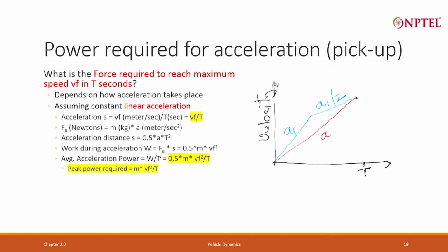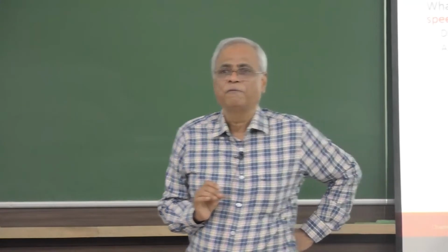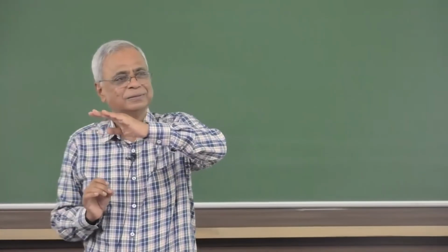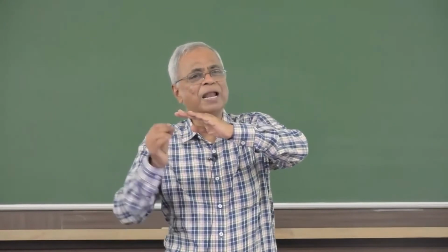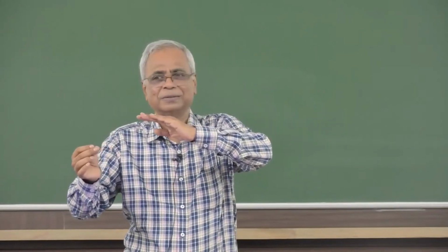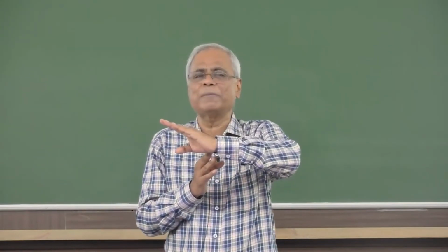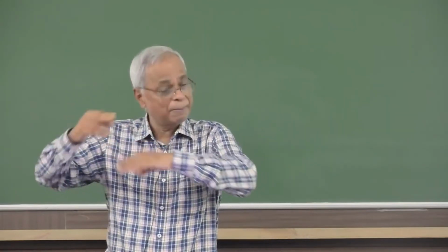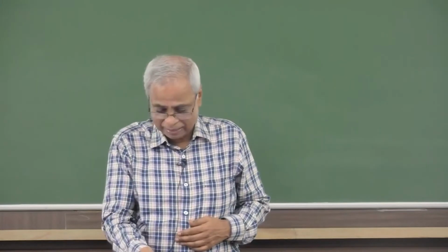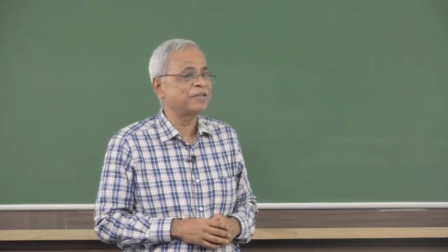So, what we often ask, do I really need to accelerate linearly? Because power requirement always will have an extra v term. Force may be constant, power will have a v component. So, if force is constant, in the beginning my power requirement is small, in the end my power requirement is very large. That is the reason peak power requirement is m v f square by t.